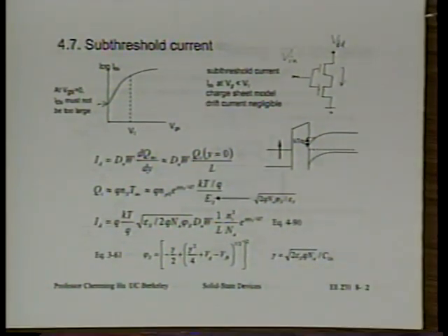And we are counting on that to have low power dissipation of the CMOS circuit. That's why we can store a lot of information in the Palm Pilot and not drain a lot of battery. Because when we are not turning on-off the CMOS circuit frequently, we don't drain a lot of current. We don't dissipate a lot of power, called standby power.